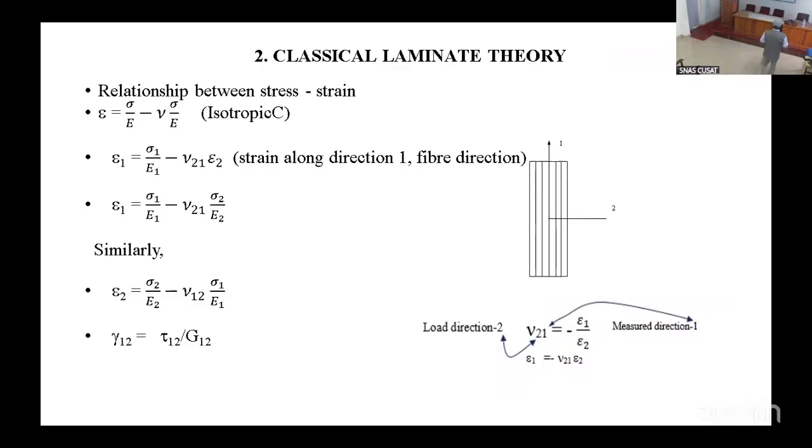So here you see, in composite material, the fiber direction is always referred to as 1 or L, the longitudinal direction. And unless otherwise specified, the load direction is along the fiber direction. That is the default. Generally people say the strongest fellow takes the load. So who is strongest? Fiber is the strongest. So in this direction only we will apply the load.